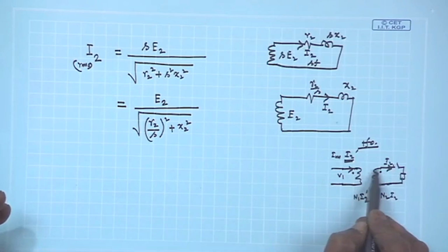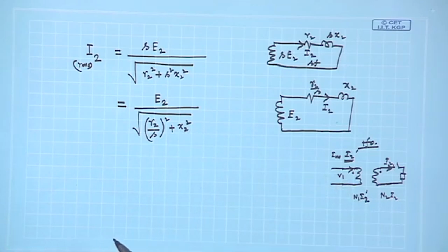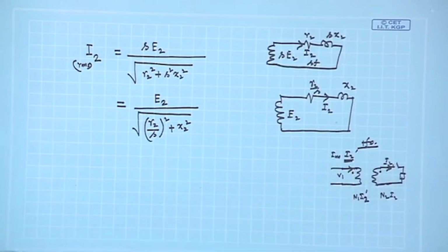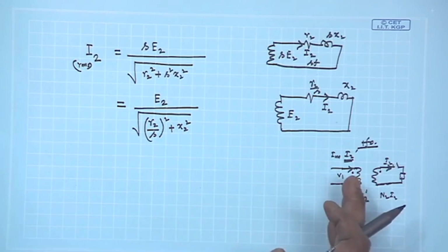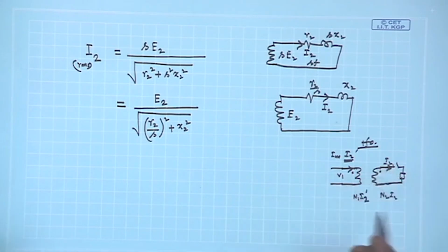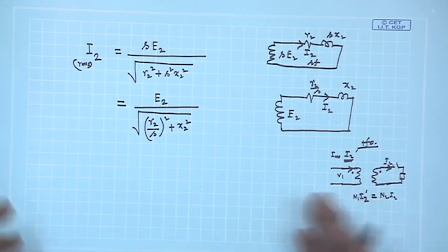From the dot it delivers, from the dot it takes current, such that the total MMF existing in this circuit is once again N1 into Im, the magnetizing current, and flux remains constant, and everything is now nicely satisfied. That is, KVL is satisfied, flux has not changed, and your MMF balance also takes place. Any extra current you draw, things will be that.